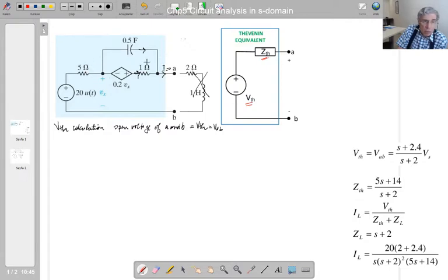We already said summation of these two currents is equal to 0, so that current is going to be 0. So that current is 0 means that voltage, by definition relation of the resistor, that voltage is also equal to 0. If that voltage is 0, then this voltage becomes equal to that dependent source control voltage, isn't it? So Vx is equal to Vs.